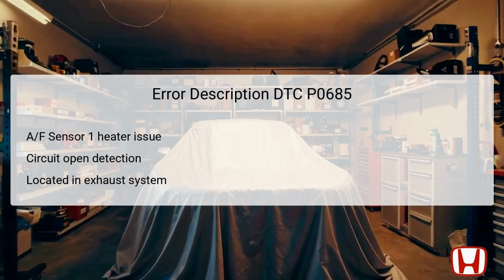The DTC P0685 specifically points out an issue with the A/F sensor 1 heater power source circuit deemed open. The A/F sensor, located in the exhaust system, is responsible for detecting the air-fuel mixture before it enters the catalytic converter. The heater within this sensor ensures it operates at optimal efficiency, especially during cold start conditions.